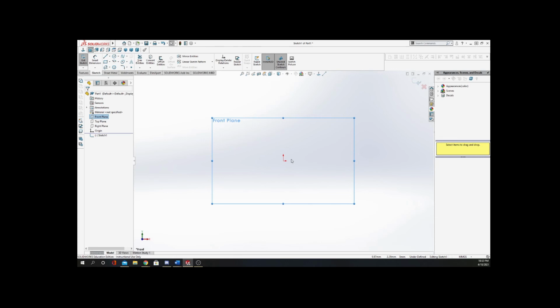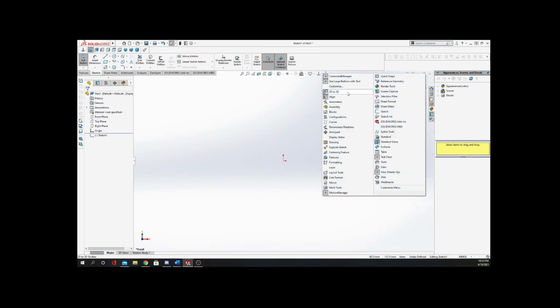And when we're drawing, to get our measurements and our coordinates correct, we want to know what this known origin is. So one of the things I like to do is to put in some reference lines. Now I've added this reference line, the center line, up here into my hot toolbar, and you can do that by right clicking up here and choosing which tools you want to add in. I customized it and added it in. So you can go through your customize menu and search for tools, or go through and add them that way.